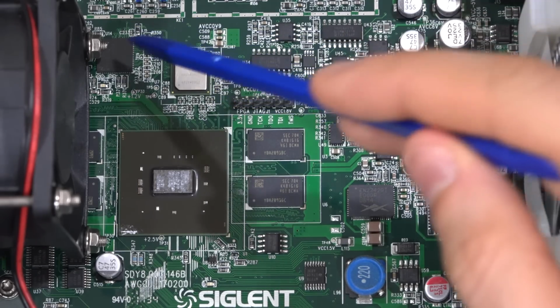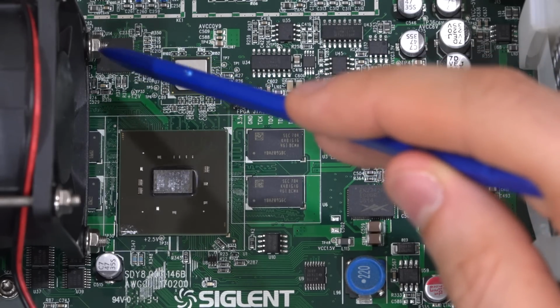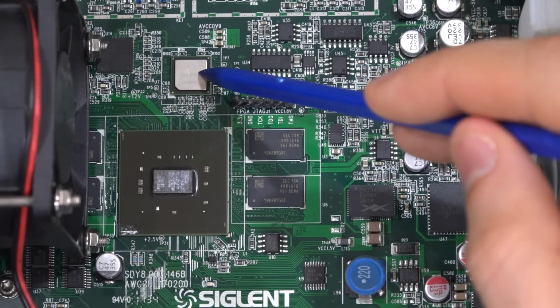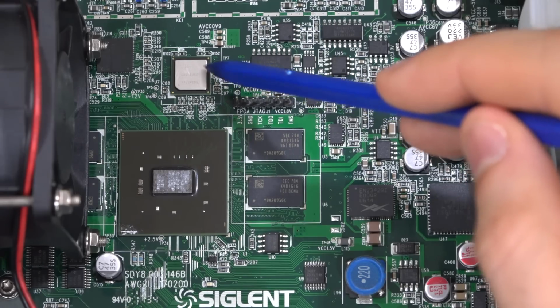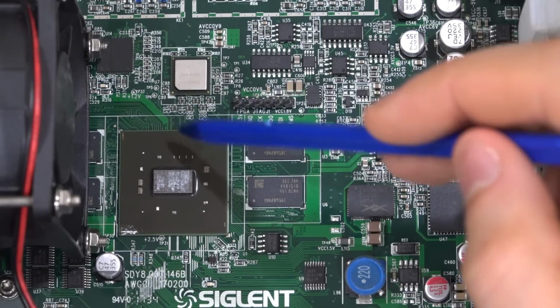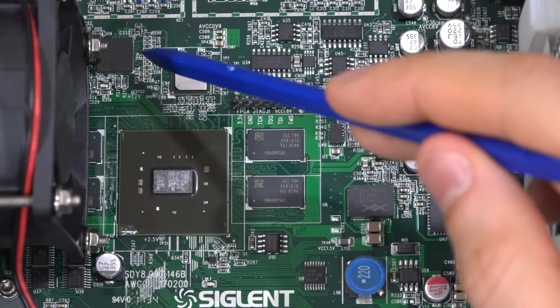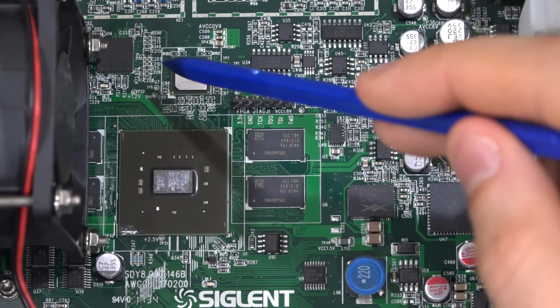And that's how they get you to design entirely with all of their components to get you to the system that you want. This PLL here is an interesting unit because not only does it create the necessary signal for the DAC's clock, which is critical if you want to get the 16-bit performance out of the DAC, it also allows the synchronization of the JESD interface from the FPGA. It allows you to generate other PLL frequencies to run other components on the board.